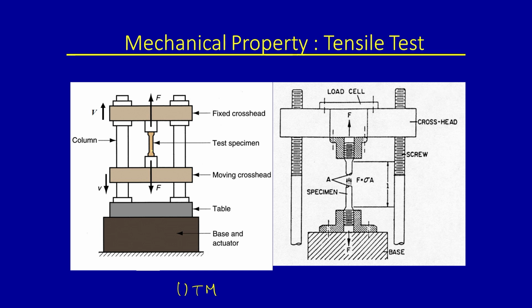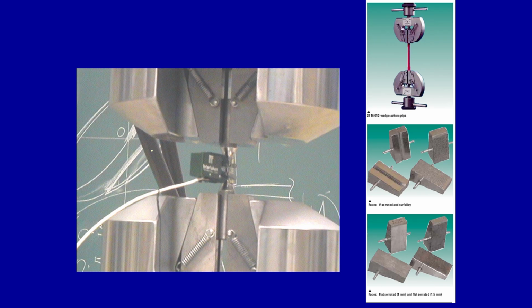So as you can clearly see, if you want to measure the strength and ductility, you need to use probes. That is very important. Here we are showing a probe which is called an extensometer, and this device measures the increase of the length of the sample. When you apply a load, the sample will deform plastically and its length will increase and width will decrease.